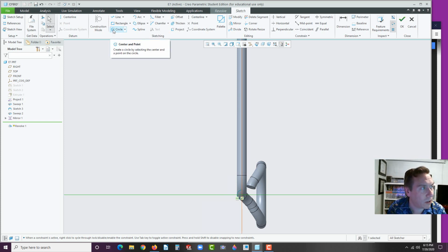Now let's draw the circle. So go with the circle over here. Get between these 2 little bosses. Look carefully where I'm at. Click. Drag out a circle and get the equal symbol. See how I'm getting the equal symbol there? Notice lower left, it's highlighting the edge. It's found that same diameter. We want the wire to be the same throughout this entire model, so that's fine.